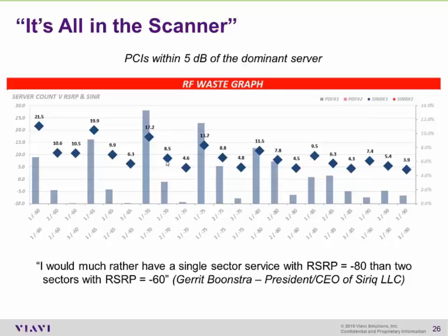It's not ideal coverage. So if you hear the commercial more bars, more places, if you're close to an antenna, great. But if it's because they simply turn up the power, that's not a good RF approach, maybe a great marketing approach, but from an engineering standpoint, with 3G and 4G technologies, you're trying to maximize your RF usage by minimizing the overlap.